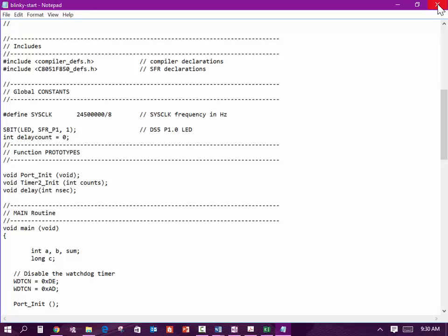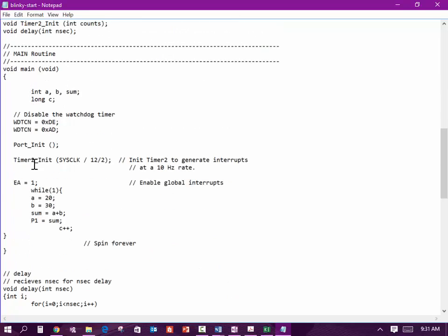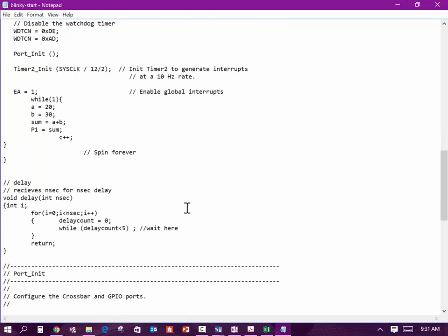But it's an equate sign. It's a symbol where this sets up an SPID. We don't want to use SPID. We want to just simply do a constant, equate. Because what we're doing here is we want to set up a port equal to that. Actually, what you would do is just say port 0 is equal to, there. In other words, instead of saying lights, you can just say port 0. So you just want to do an equate.